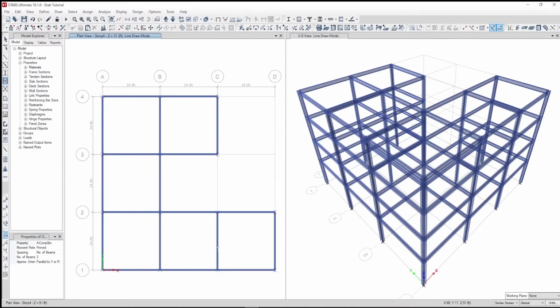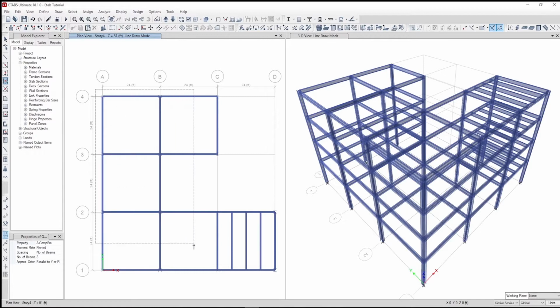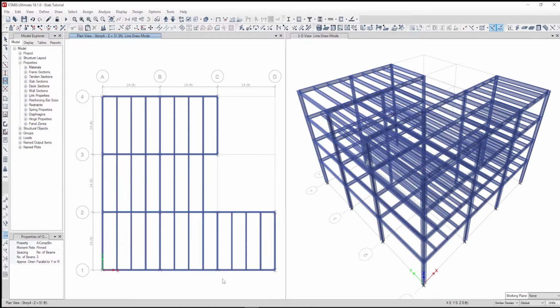Left-click within the frames to draw the composite beams, or draw the selection box over the frames where you want your composite beams to be drawn. To remove composite beams, use the intersecting line tool to select the beams. Left-click and draw the selection line to intersect the beams for deletion. Once your selection line intersects all objects you wish to select, double left-click to select them. Press the Delete key on your keyboard to delete them.